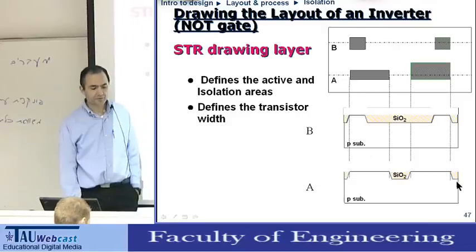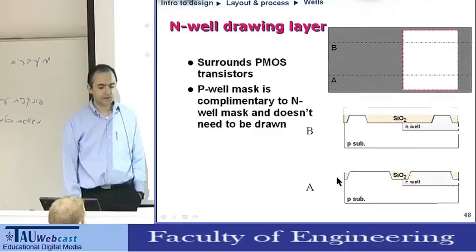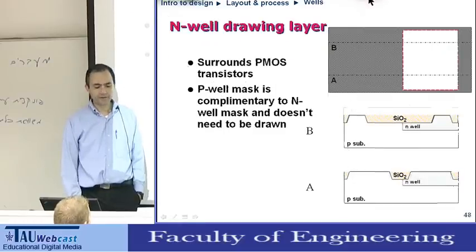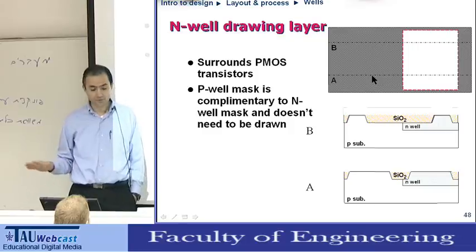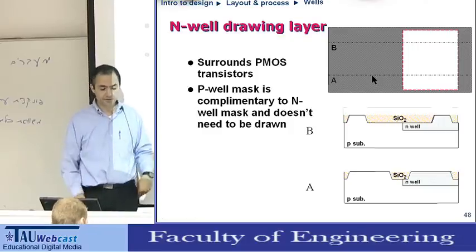Okay. Why do we polish before we move to the next step? One of the reasons is when we do lithography, we want everything to be smooth. And also later we will build layers and layers and layers, so it's better to build on smooth.